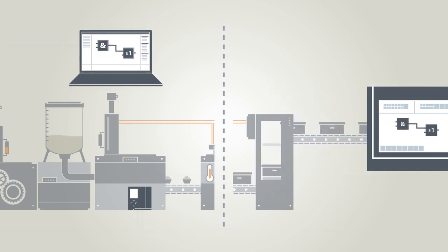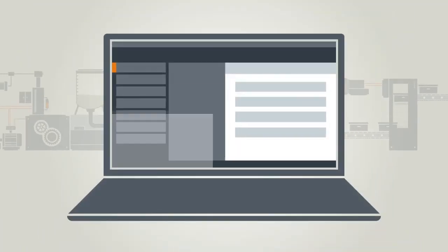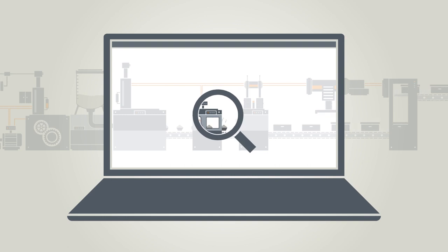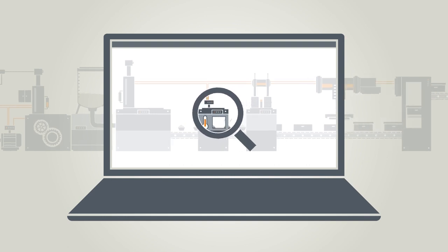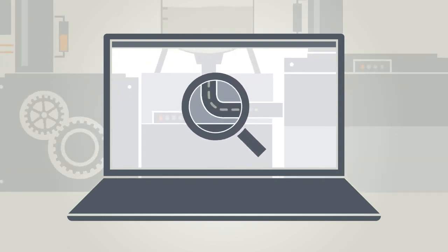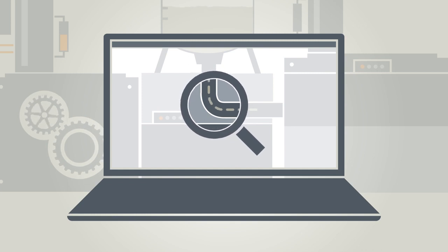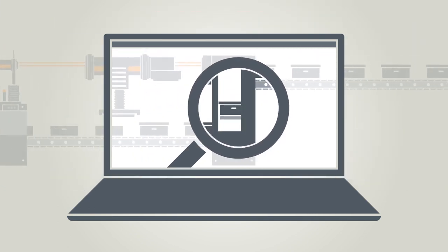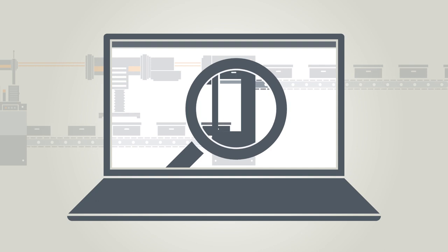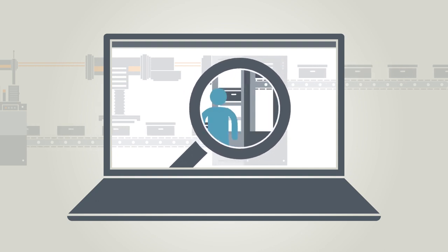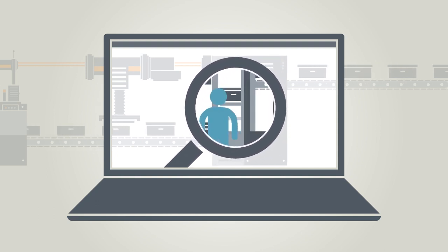For supervision, you have a choice of various types of supervision in the TIA portal. With operand supervision, you primarily monitor static signals, such as pressure, and control supply voltage. Interlock supervision keeps track of whether the necessary releases exist for the movement, such as whether the protective door is closed.